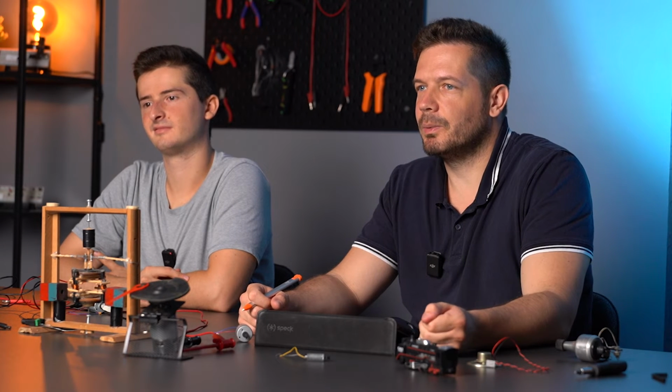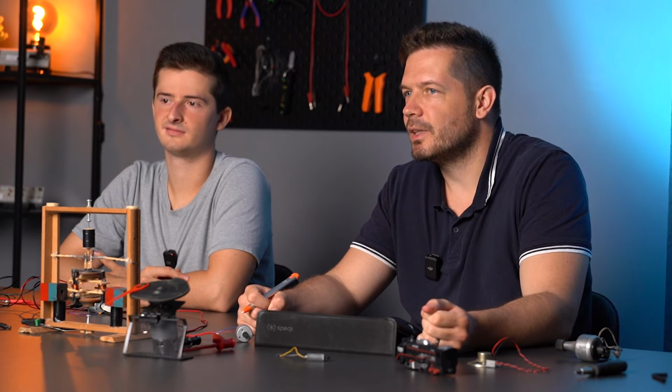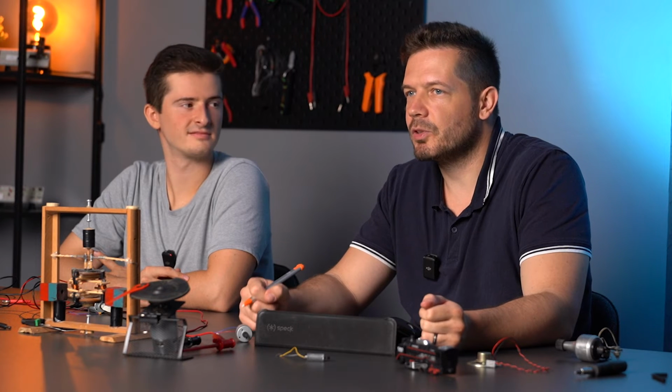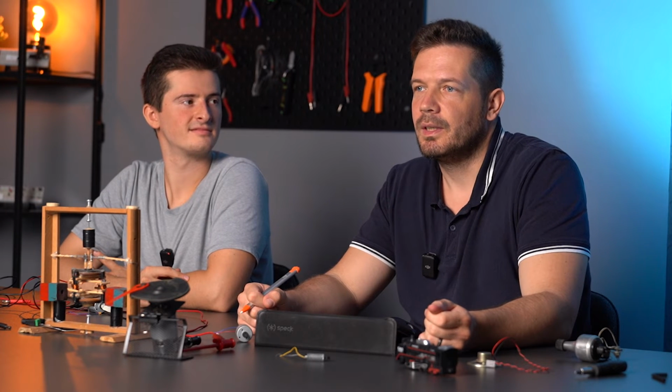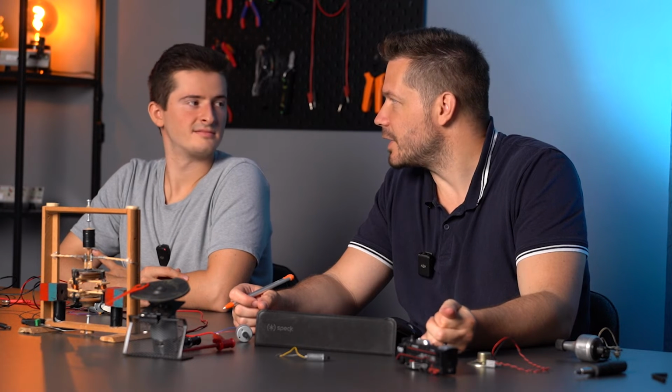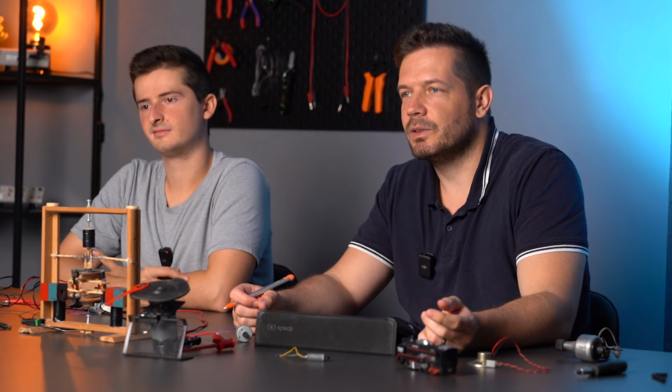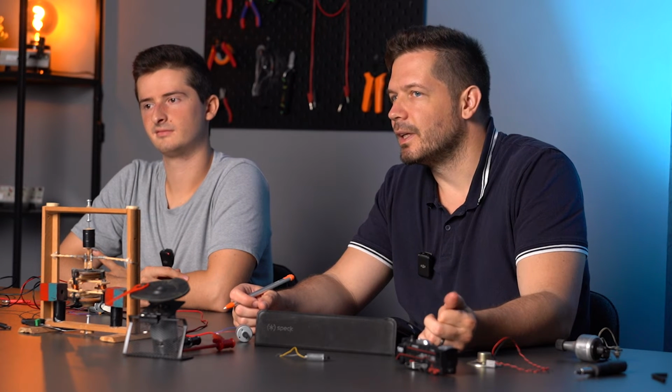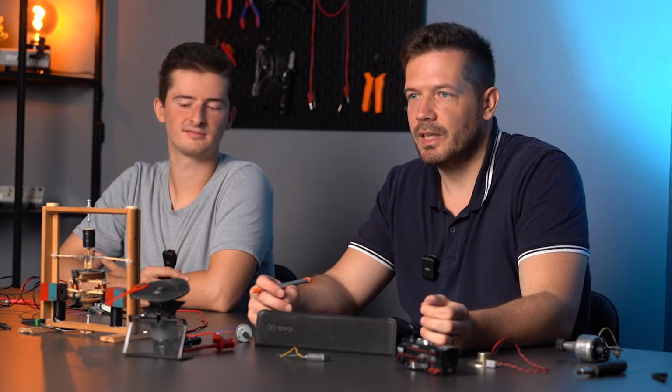If we place a second conductor perpendicular to the first loop, which is connected to our direct current source through the commutator at every quarter turn, the pulsation of the torque will be smaller. If we increase the number of loops, we'll get a relatively smooth rotation.